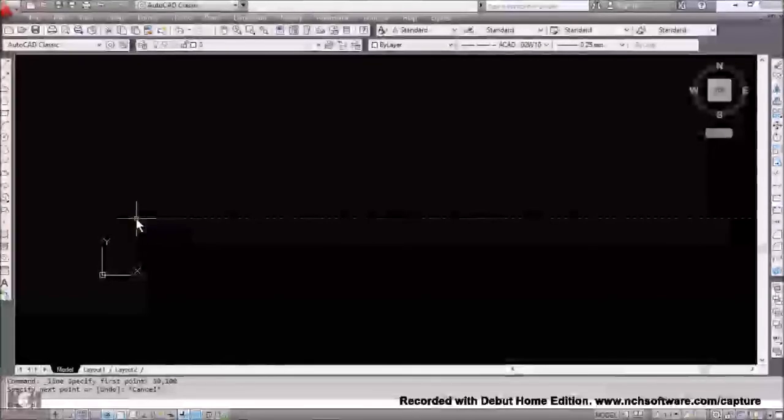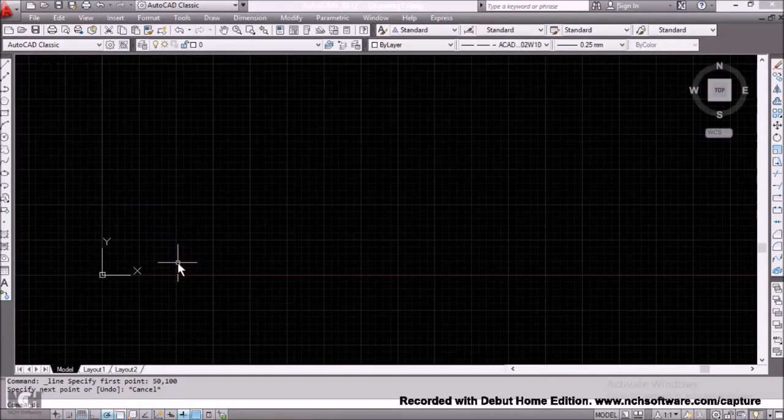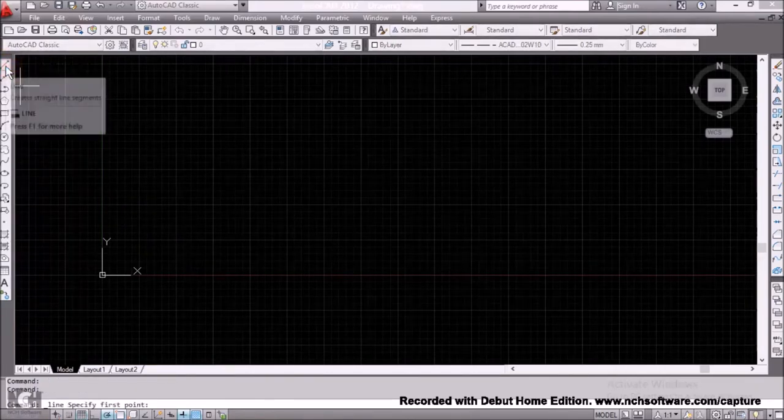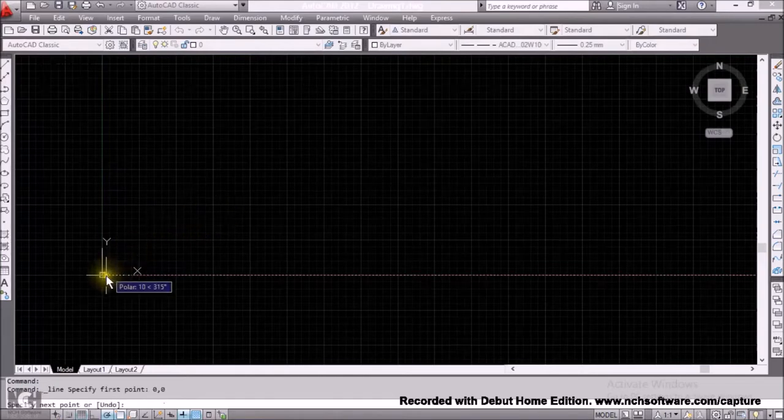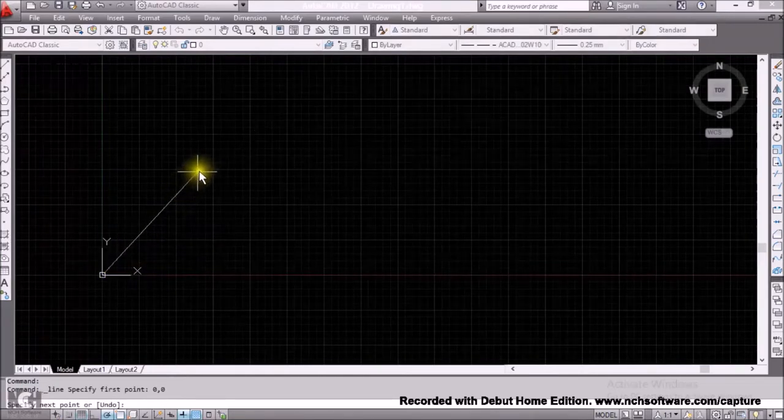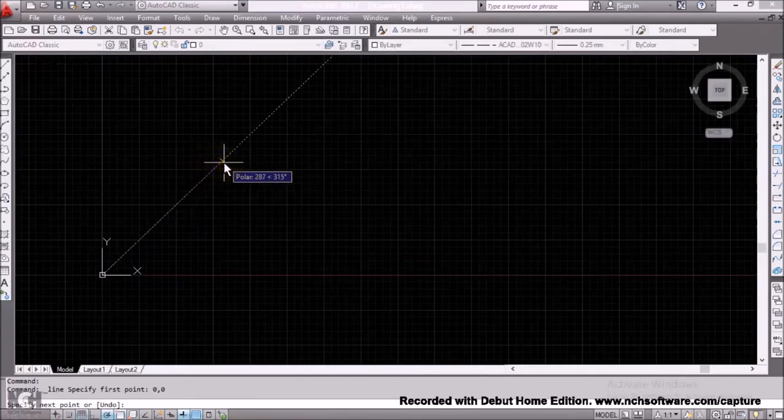And if I want to locate the origin of our coordinate system, I'll still use this method. So I'll select this line, and I'll type 0,0 on my computer keyboard, and I'll press enter. Now this is the origin of our job. That is the job of the absolute coordinate method. So it helps you locate coordinates of points making reference to the origin.